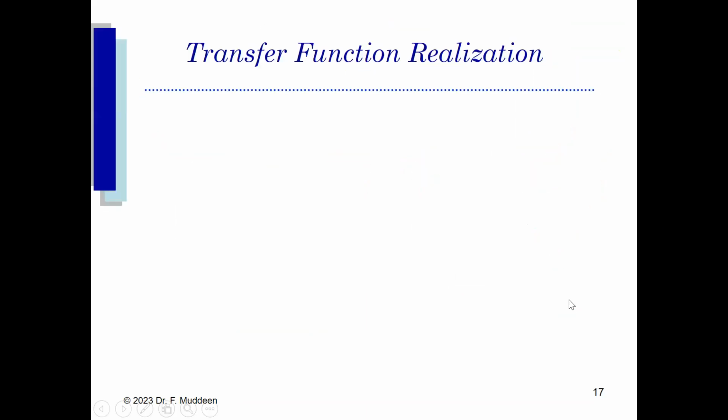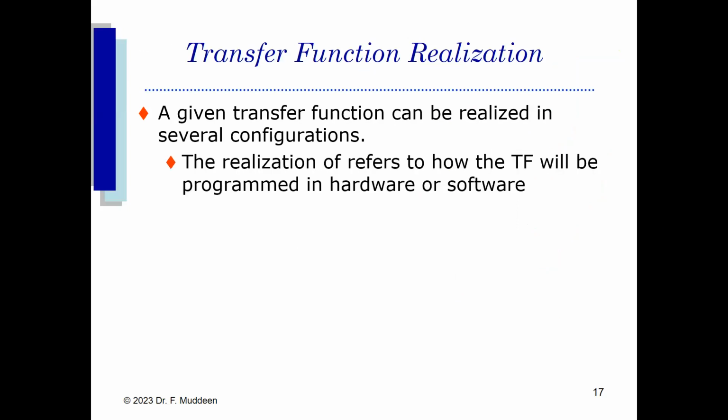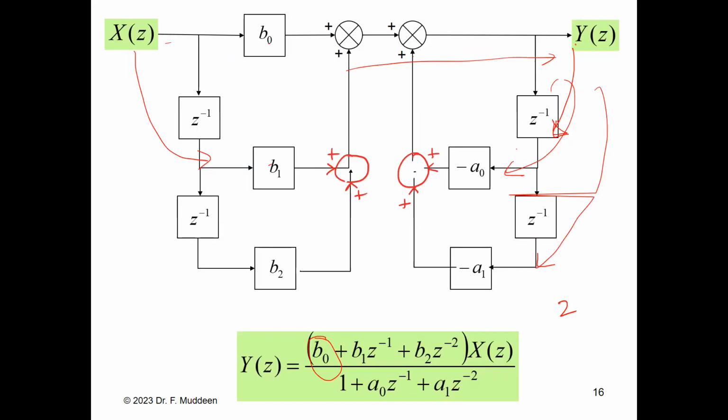These are all called the direct form realization. In other words, as you get a transfer function, this is how you could implement it. It's not the most efficient way, as you'll see in a little while. But if you want a simple process, you have some data coming in and you want to manipulate it, this is how you take sample by sample processing, in other words.